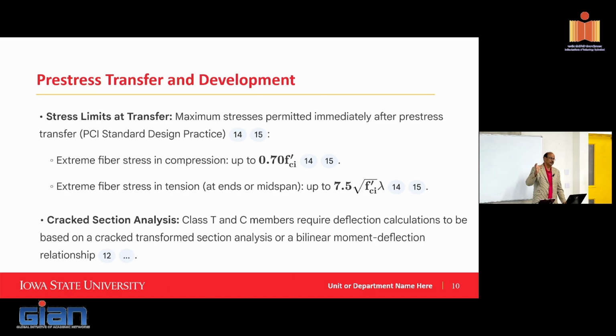That's what I typically call the transfer length. But that number may not be the same as what they call the development length. Are you familiar with development length? I think you learned it in concrete design. You learn development length, right? The same thing applies to the prestressing strand as well, right?